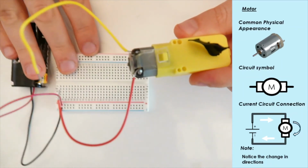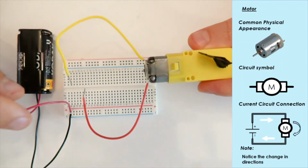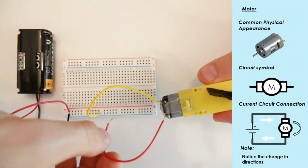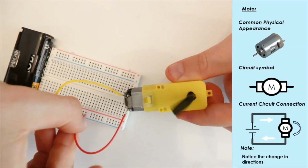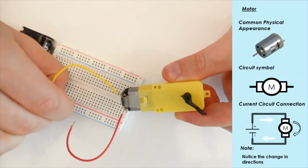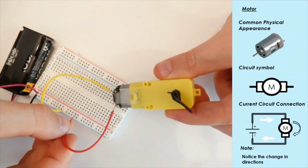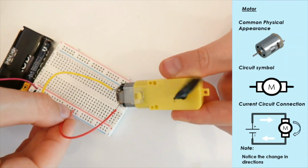So now if we take a regular 3-volt battery pack that we've put in series here, and we connect our yellow side of our motor to the positive and our red side to the negative, like so, you'll see we have an anti-clockwise rotation. Now if I swap over the yellow now to the negative and the red now to the positive, you'll see we now have a clockwise rotation.